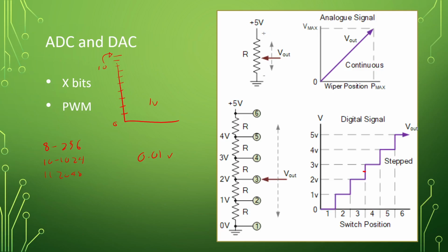It's not just, oh yeah, give me an analog sensor, my range is within that, that's perfectly fine. Well, it might get you close, but is it close enough? Depending on your situation, maybe not. Maybe you're heat treating something and you need to get it to a very specific temperature, so it's a specific hardness. You don't want to go too hot, and your resolution could screw you up on that. So you do have to be very careful about that.